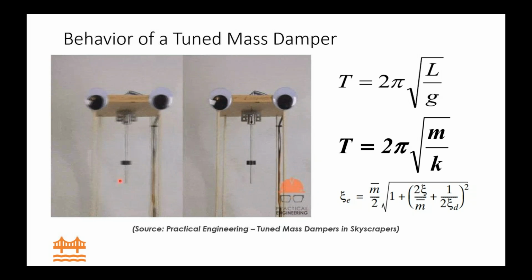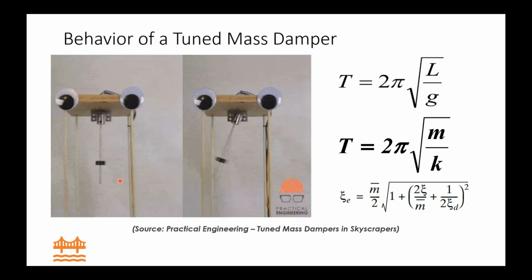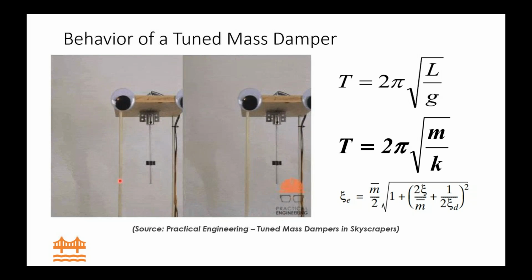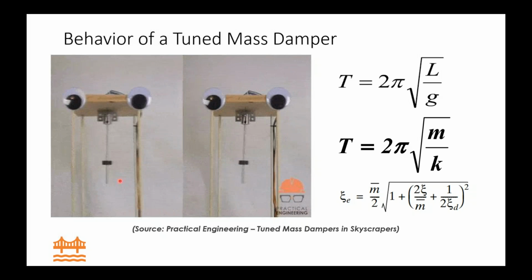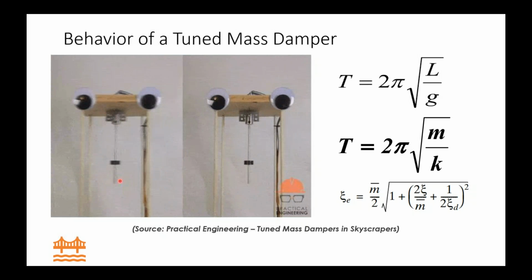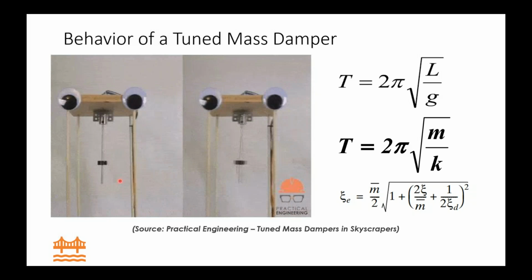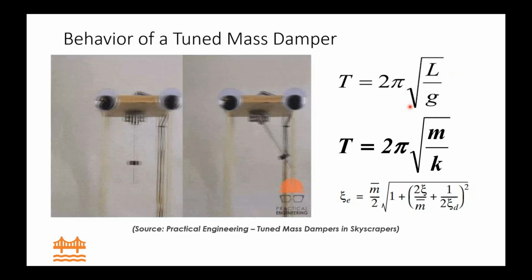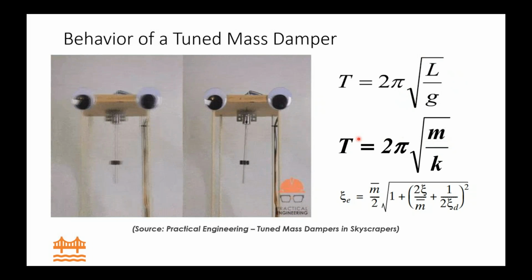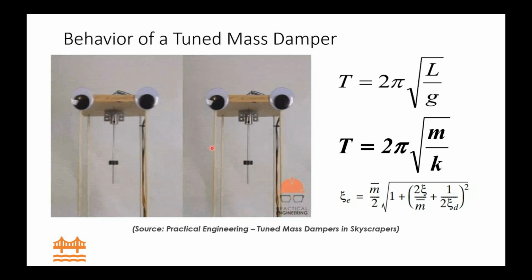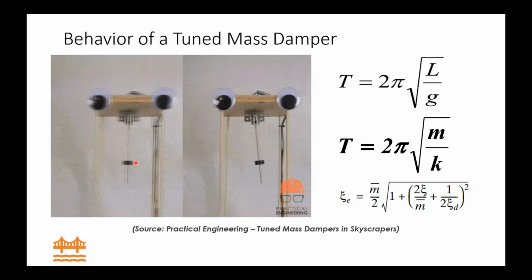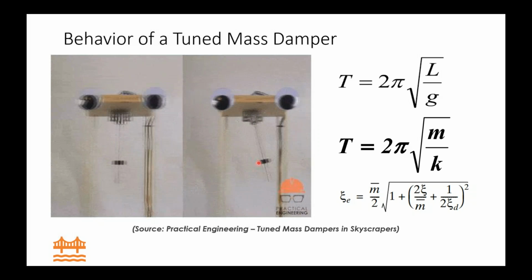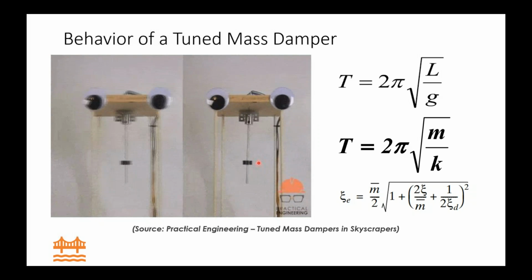It's not very common in bridge design to have lateral vibrations, but in buildings, usually skyscrapers, there is more of a tendency for lateral vibrations, and that industry has developed what they call a tuned mass damper, or a pendulum tuned mass damper more specifically. The way it works is you've got a mass on the end of a pendulum, and we can tune the pendulum based on its length to match the frequency of the bridge. You can see in these two figures that with the pendulum fixed, the vibration does not mitigate. In the one where the pendulum is free to rotate and dampen the bridge, it damps out much quicker.